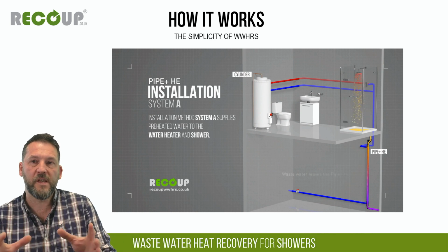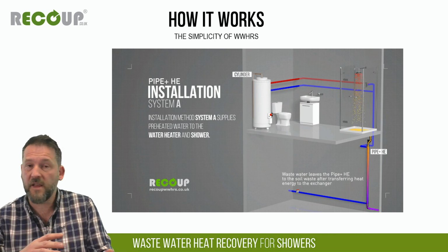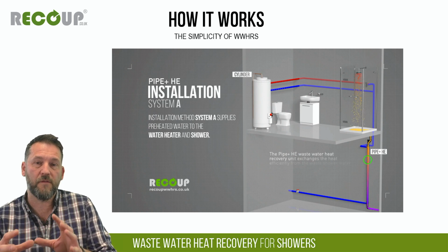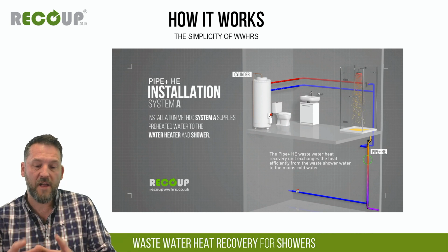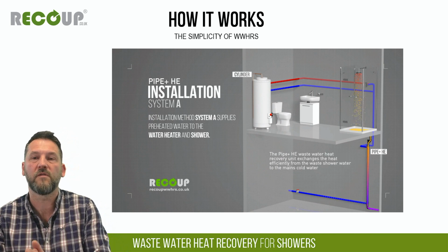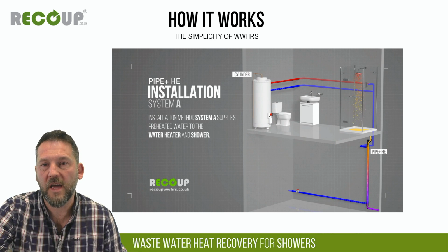Of that 40 degrees coming out the shower head, about 85 to 90% of the heat energy normally goes down the drain and is lost out of the building. So it's a big energy loss, and there's a lot of thermal energy locked up in shower wastewater. And it's exactly that we use to preheat the incoming cold. So what we do, and as you can see here, we've got a heat recovery pipe.